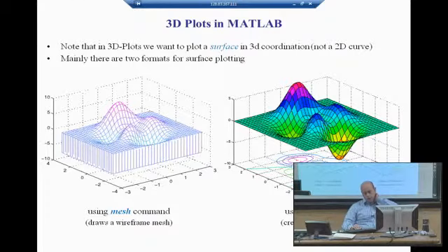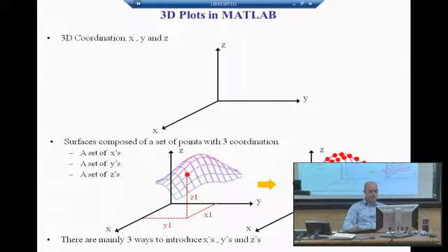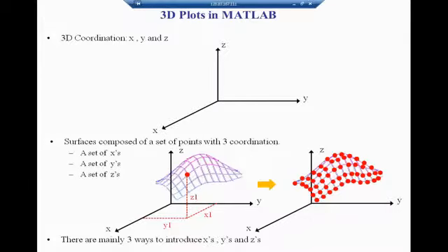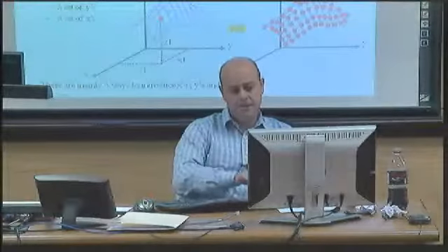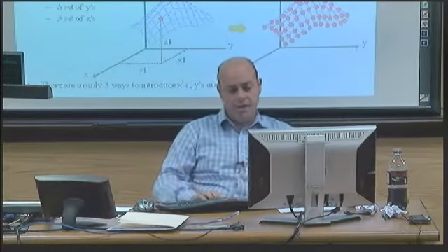So these are 3D plots. And there are, I think, dozens at least of different commands to create 3D plots. I'll just cover a couple, the ones that I think are useful. You can use the mesh command, which creates a 3D plot that looks like a mesh. You can use the surf command, which creates a surface plot. There's also a contour plot you can make. Basically, the idea is that you're plotting z as a function of x and y, for example, or z could be temperature, whatever. But the point is that it's a function of two different variables like x and y.